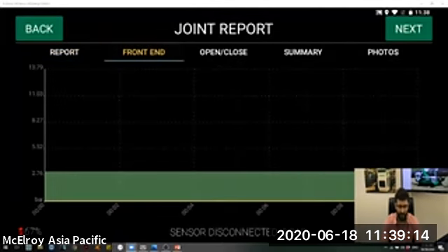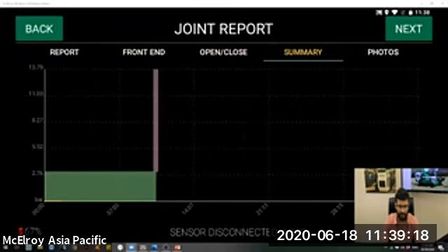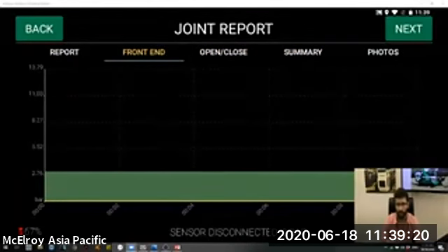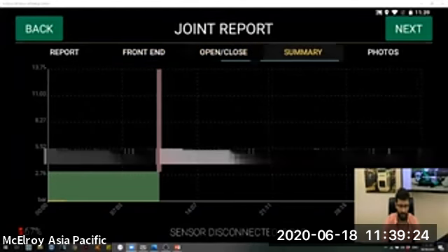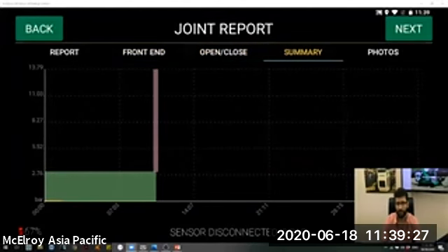And also you can check the graph. Obviously, the graph here will not show properly because I was not reporting real pressures. But in here you will. The Datalogger will show you the colors with the graph, so the operator can actually correlate what he has done with what the standard was recommending for that pipe size with that machine.